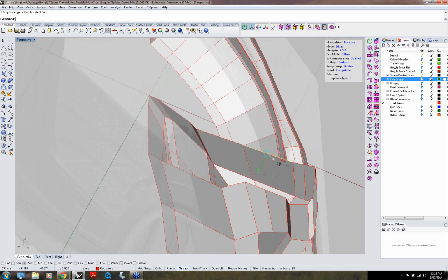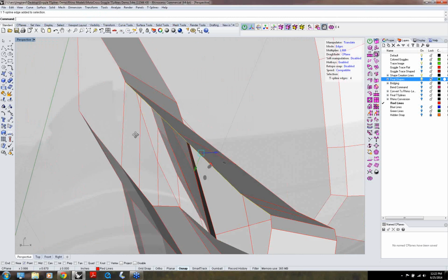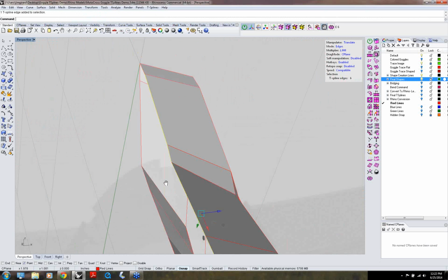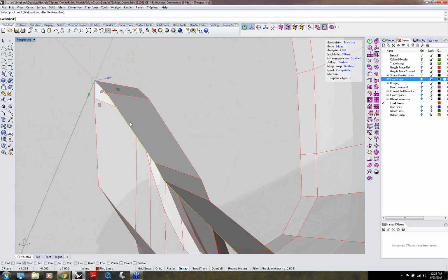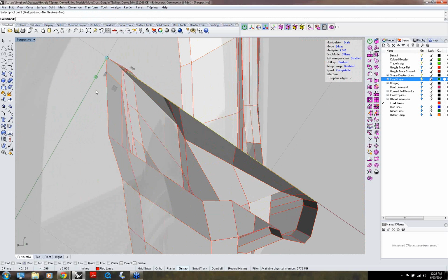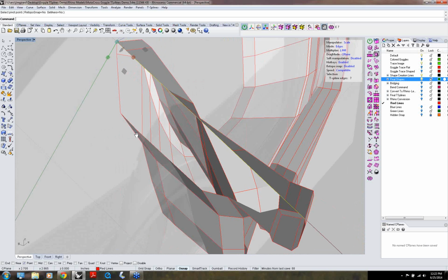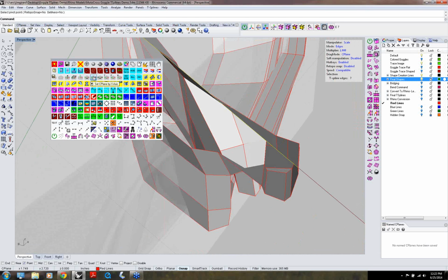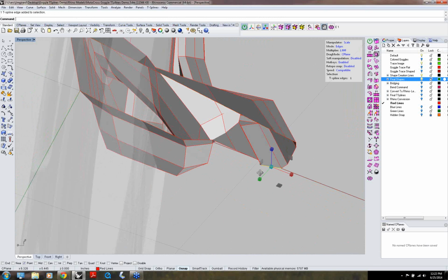And then I take the edges and select them all. And then I use T and show where I want my manipulator. And with the R hotkey, I go into the scale command. And now you'll watch how I take that edge and I just clean it straight up. I just pull it right where I want, a nice straight edge. And then I do that same process here. I'll just put 2 points and that point there, and pick all the edges in between.